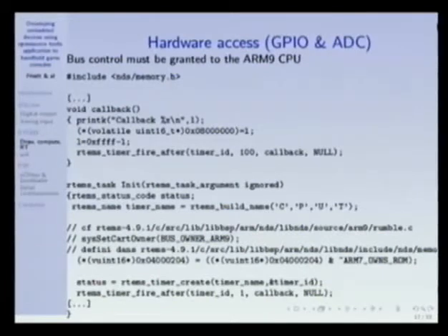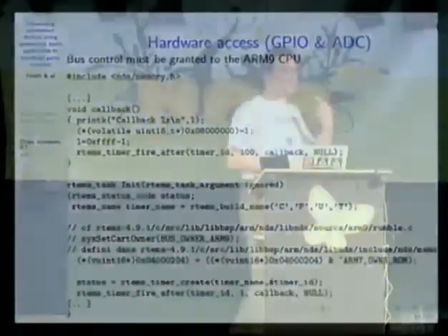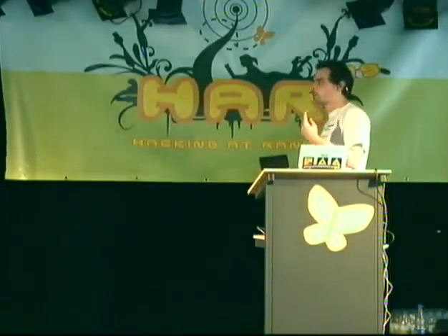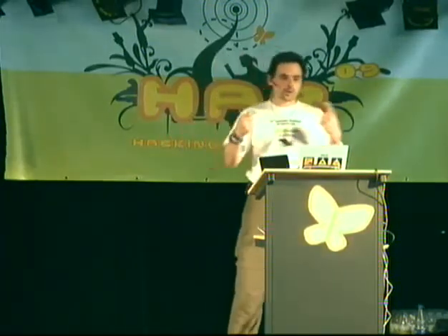Now, again, I want to access hardware, and this is usually done by writing to this address space, as we did exactly before under Linux. And if you do this, you have a bad surprise because it doesn't work. The bad surprise comes from the fact that this bus, I mentioned to you that it's a Game Boy Advance compatibility bus, which means that it's the ARM7 which is working on this bus. And DS Linux was assigning the bus automatically to the ARM